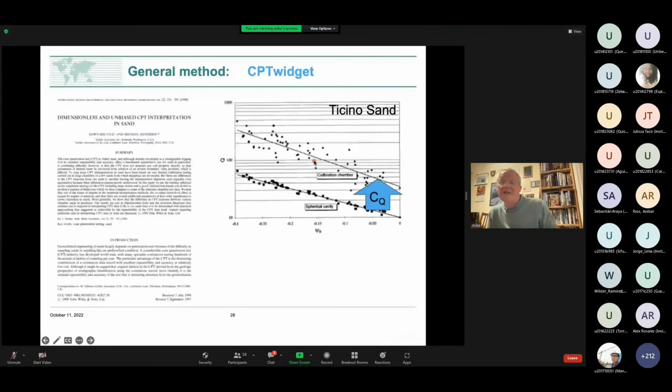So how do we establish the limit pressure? Well, very simply, we do a mathematical cavity expansion in sand. And this is using critical state theory, and we compute this. And we then look at the relevant chamber testing, and the ratio of the trend line through the chamber testing to what we've got with our mathematics is our parameter CQ. Nice and easy. But the beauty of having done this now is we have a methodology we can apply to soils of different properties.